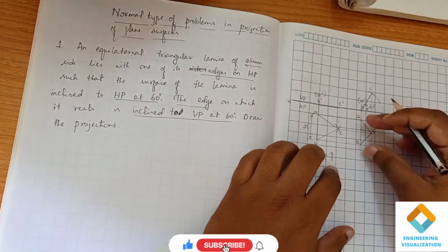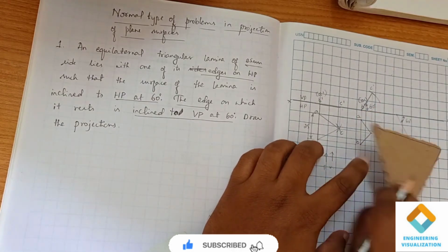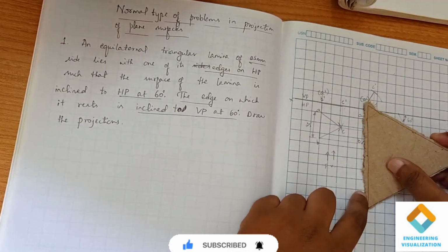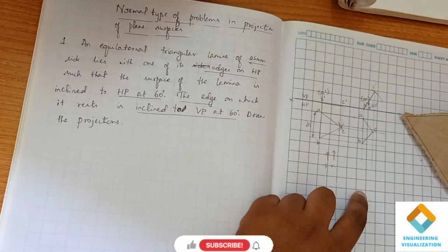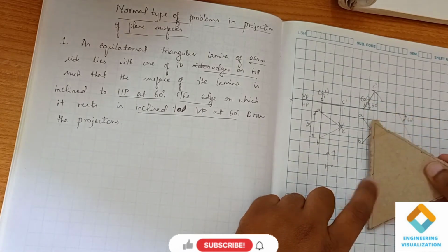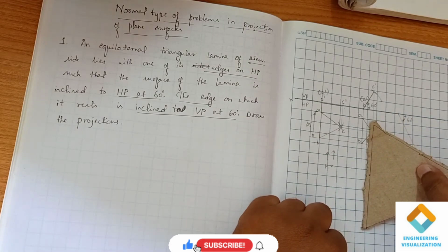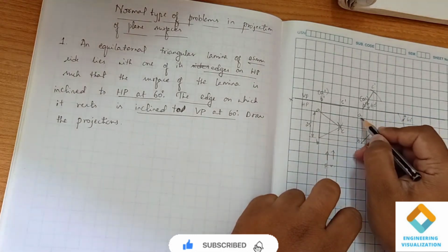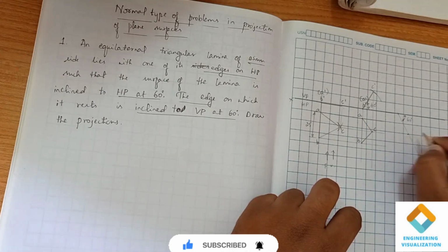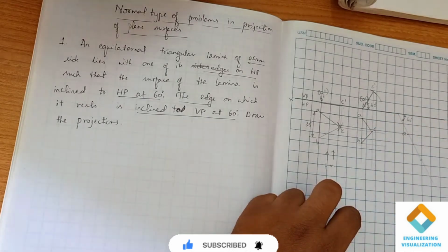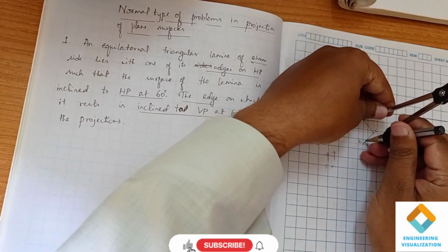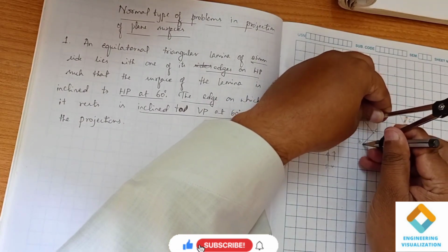So now what we do, we are taking this AB edge. This is our resting edge. We'll take this AB resting edge and we are going to place it like this on the angle line. This is how we make the triangle inclined to VP. First you mark a reference point A. Now we'll be measuring this length AB, so transferring the inclined view here. So this is the inclined top view, not the first position.